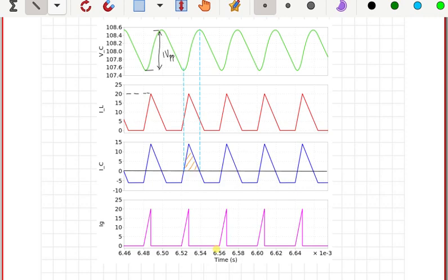except that now you can see that your source current is a very peaky waveform. Okay, so you see that it goes from 0 to 20 amperes and it only appears for a very short duration. So this current actually appears for the duration of D, right? And so we have already calculated what that D is. So this duration is just 0.1905 times Ts. Right? So you see that there is a very peaky current which appears only for a very short duration, right?